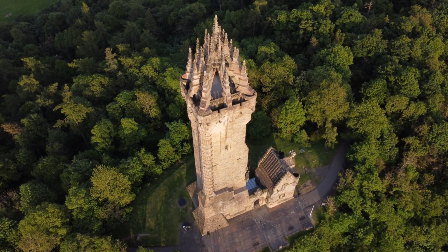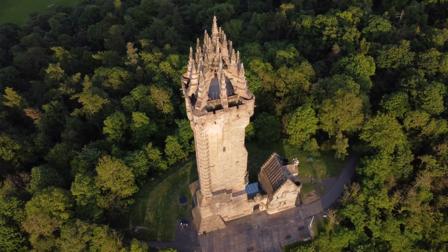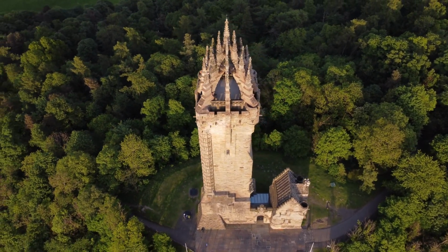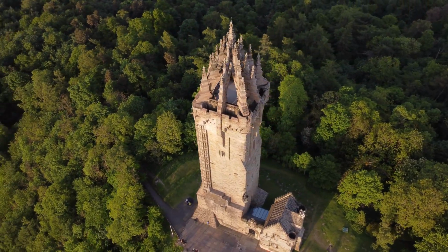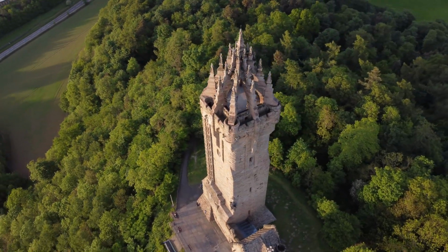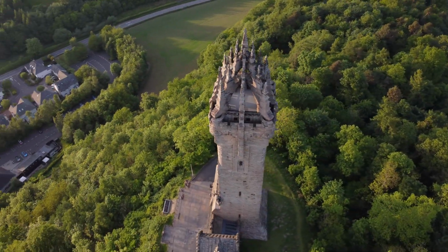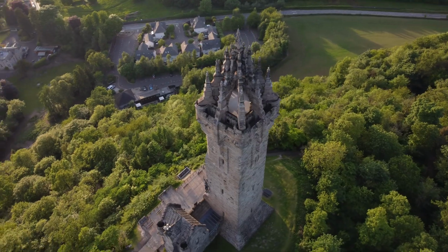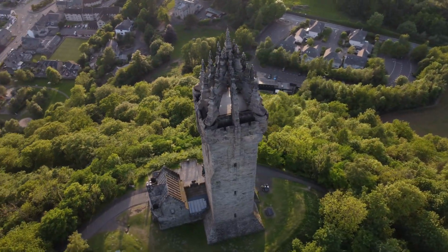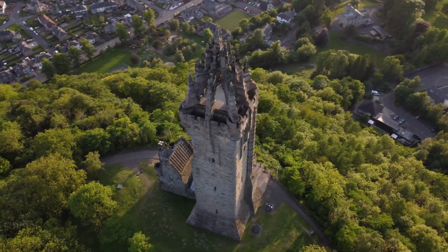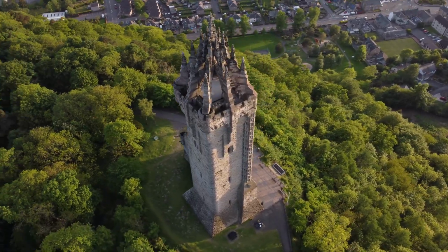This part of the video shows how I made the model. On site, I fly the drone for about 30 minutes, capturing a circular orbit around the site, like the one on the screen. This video is then brought into Agisoft and split into frames.